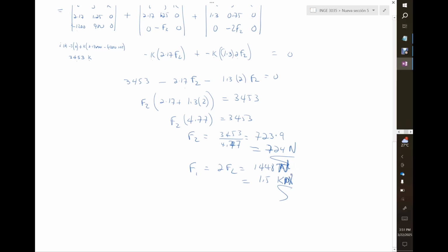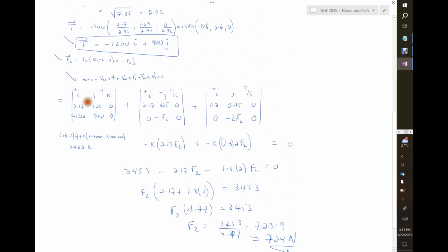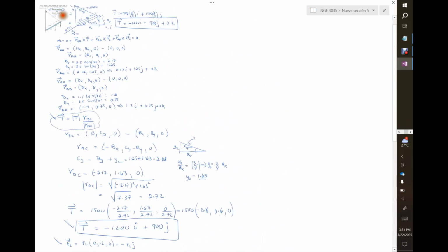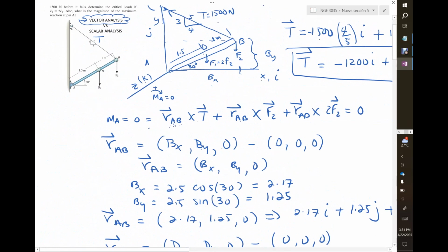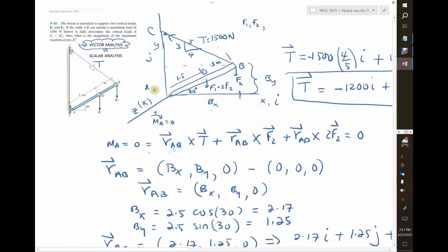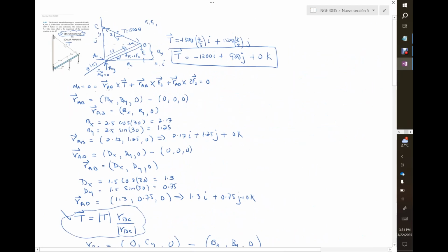At least for the force. And so we got the force. Now to get on our free body diagram, let's see where it's right here. Something got deleted here. I don't know what happened, but we can put it back. What was deleted is a force here called AX and another force here called AY. So to get what's happening on the pin here, we need to find out what AX and AY are. Let's do that math somewhere here to make this easier.